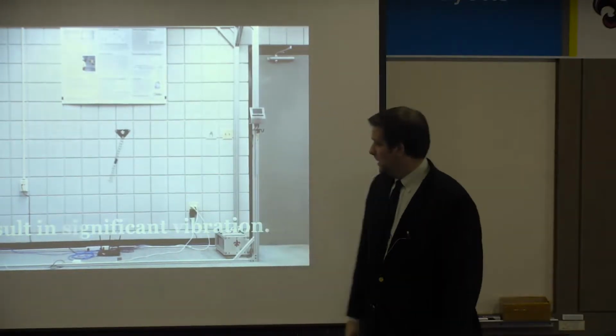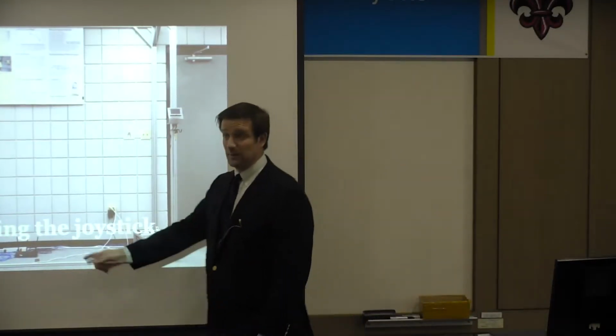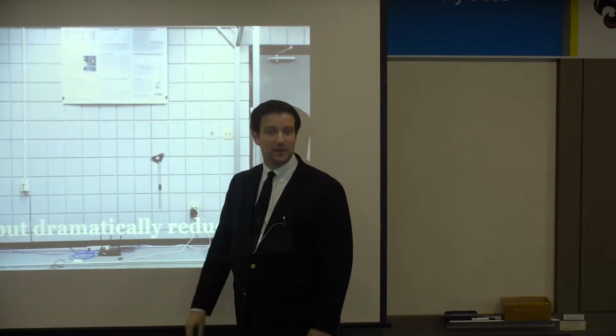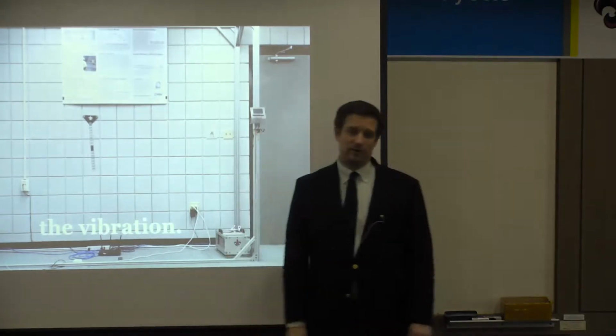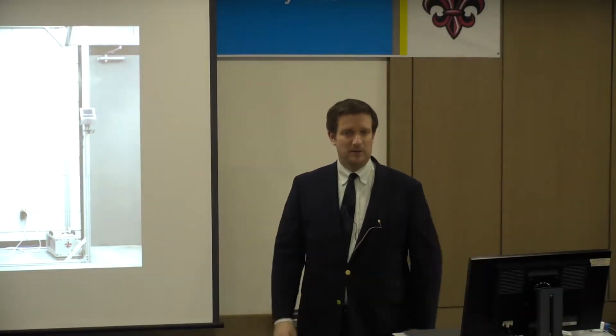Right? Then we're going to turn on the input shaper, and we just designed the input shaper for the pendulum. Right? So you see the rocking of the plate doesn't go away. I haven't designed an input shaper for that in this example. It's just the pendulum I'm able to move around without much vibration. We can and we do design the input shaper for the rocking of that plate too, but that's not in that video. Okay?